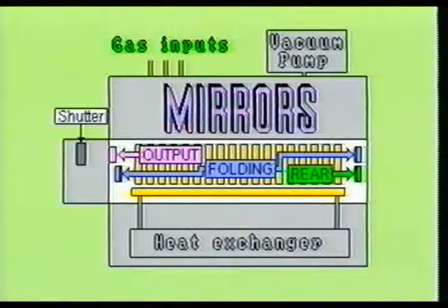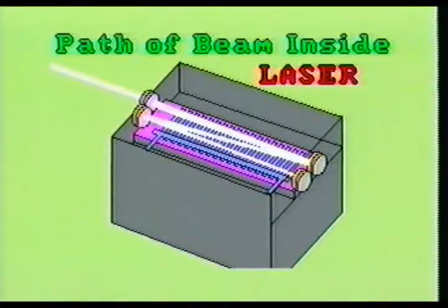The CO2 gas laser will generally contain a series of mirrors in the optical cavity. There will be a rear mirror, 2 or more folding mirrors, and an output mirror. The output mirror is often referred to as an output coupler. The rear mirror and the folding mirrors will be 100% reflective, while the output coupling optic will be about 96% reflective. Notice that the beam originates off the rear mirror, then reflects off the 2 folding mirrors, then exits the output coupler.